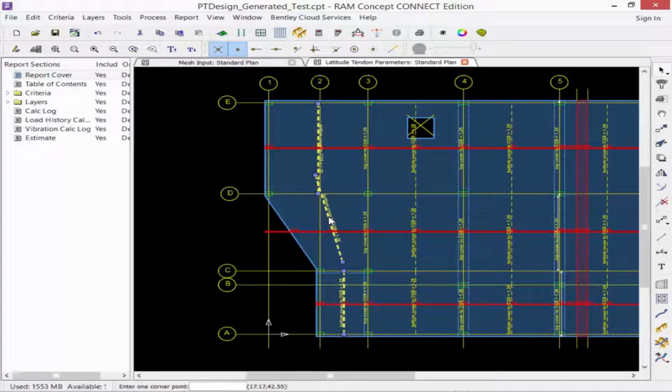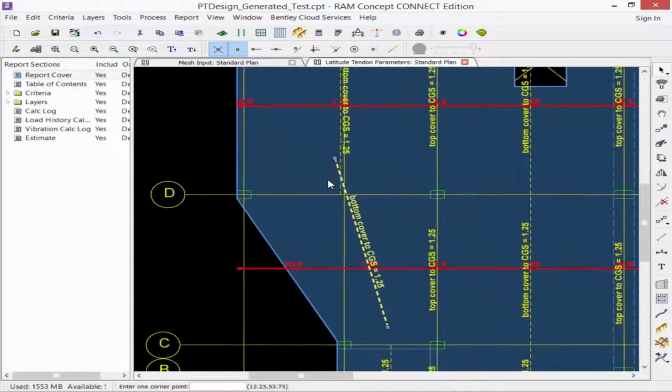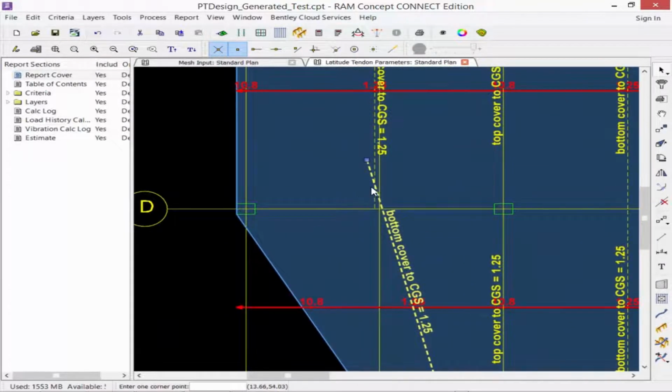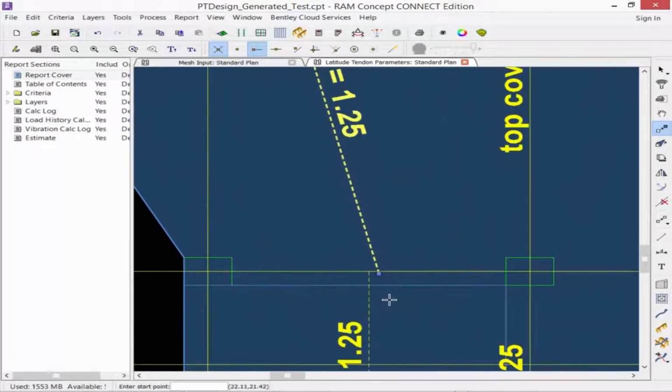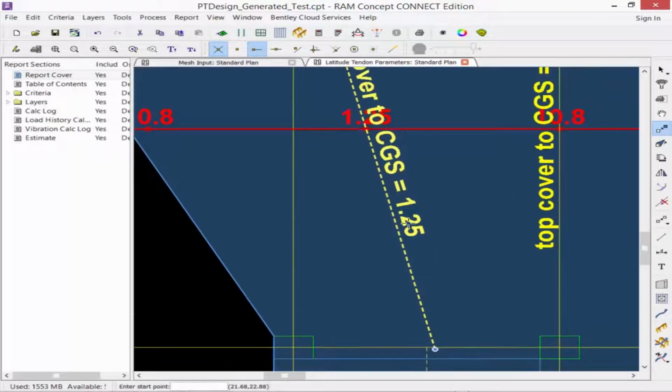So I'm going to go ahead and double click on this polyline. And what I'm going to do is I'm going to move it back to its intersection point. Now, it might be best to zoom in on your screen in order to get a closer view. And again, you can use any of your snap tools in order to achieve what you want. I have this polyline selected, and I'm going to go ahead and just use my Move tool. And I'm going to move the end from there to the intersection point, which is basically going to move it down.